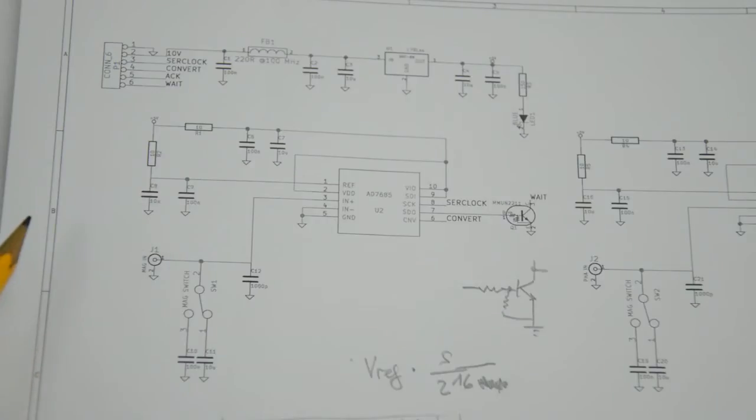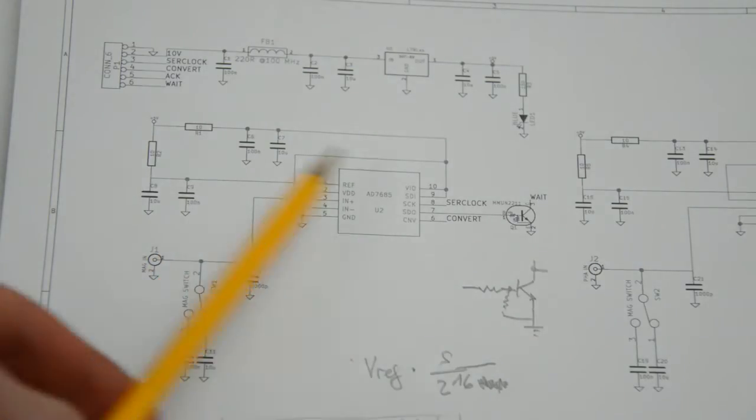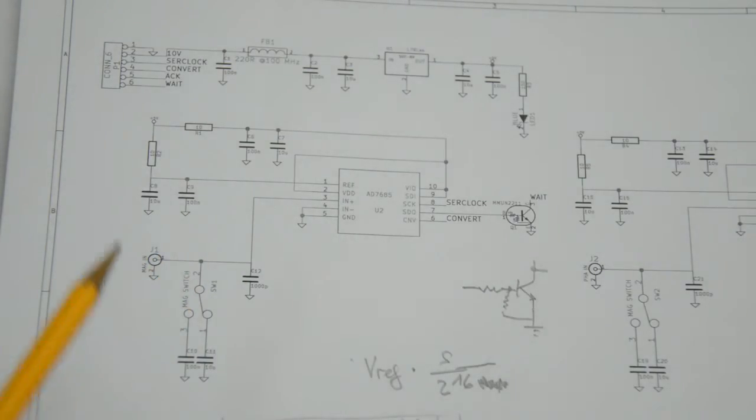And these 3K form RC low-pass filters with these shunt capacitors here, and that smooths out the measurement, and really this is the way the video bandwidth is implemented. Just by flicking the switch between two different capacitors, you get two different RC time constants, and also two different degrees of smoothing that is applied to the measurement. So you're actually measuring a filtered voltage here.